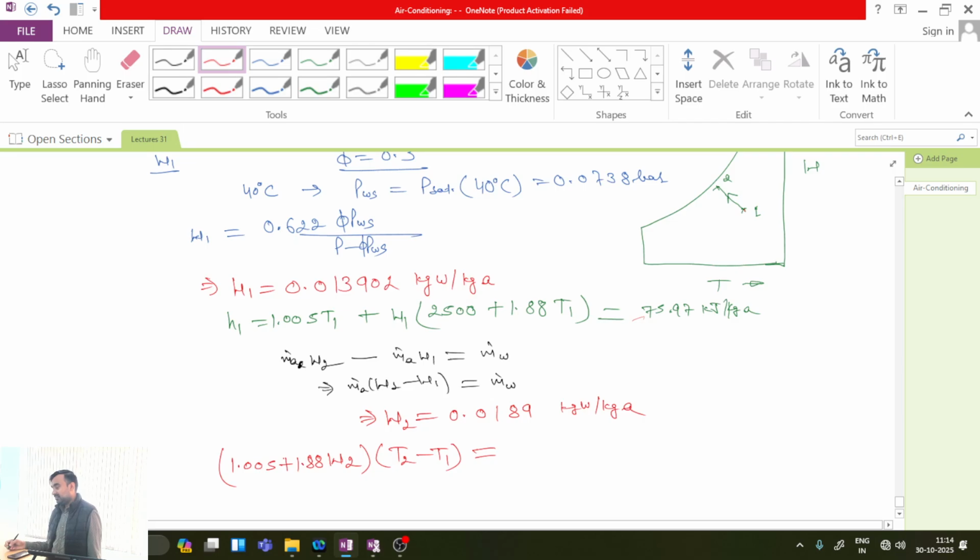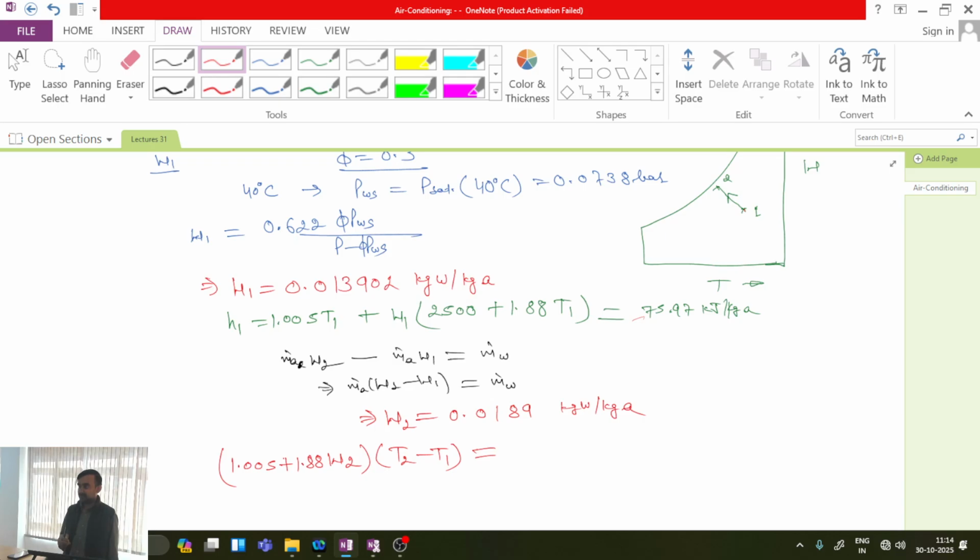Please tell me. I have given you one equation where we discussed three cases: HW equal to HG at T1, HW greater than HG at T1, and HW less than HG at T1. So that is the equation I am asking. (W2 minus W1) into (HW minus HG at T1). What is HG at T1? Simply H1 in our case, which I have just calculated.